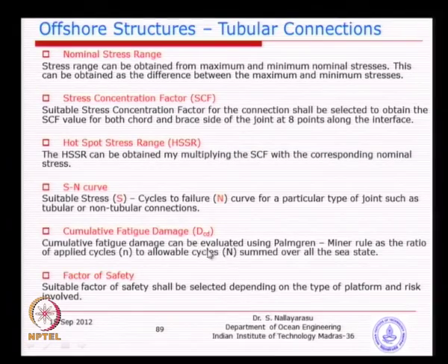Of course, the SN curve is not something that we want to generate, which is time consuming, involves a lot of money. So, basically we have to rely on the SN curve generated by the agencies like codes and standards or institutions governing the country. They have already done that exercise, every country has got. So, basically you could use that information without much worry. So, once you have this, then you can go and calculate the fatigue damage.